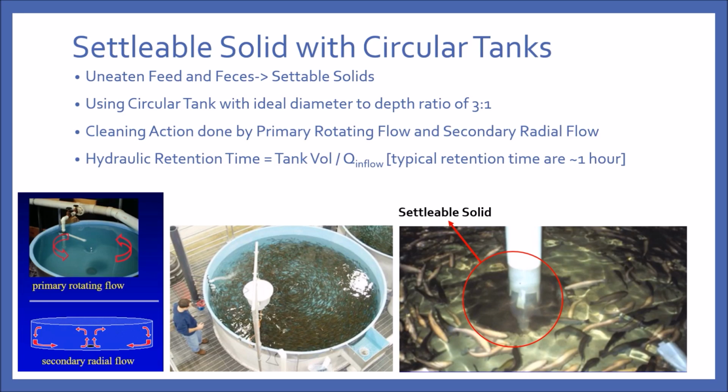As the cleaning action is usually achieved by primary rotating flow, which forms a vortex, and by secondary radial flow, which is in the form of a teacup effect. Combining these two cleaning actions, settleable solids such as feed and feces would not accumulate in the tank.